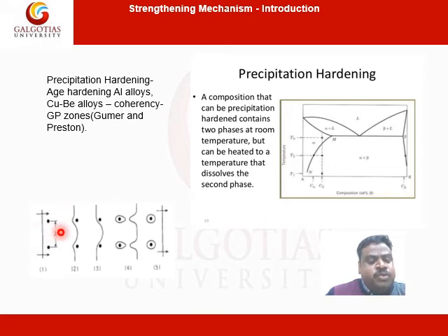When a dislocation passes through, it bows or bends before the dispersed particles. They bow more, they leave a loop and they pass through the particles. What happens? This loop, when some other dislocations pass through, they have to exert more energy, more strength, to pass through this. So the strength of the material increases. This is known as the Orowan mechanism. So we get the increased strength due to precipitation hardening, at the same time with increased percentage of alloying.